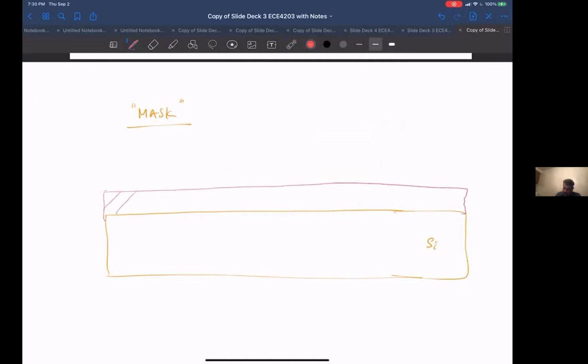And so this is something called a so-called photoresist. And the reason, we'll see why it's called photoresist. So it's like an organic material. When you're putting it on the silicon, it just looks like a liquid, a thick, syrupy liquid. Okay, but it's very much a liquid. And the way you put it on is through spin coating.